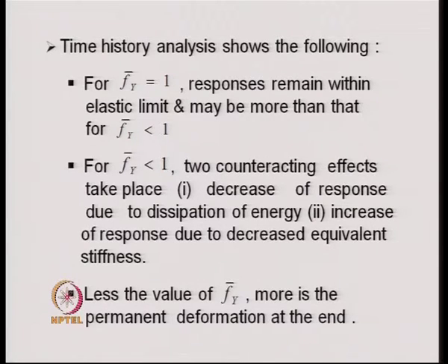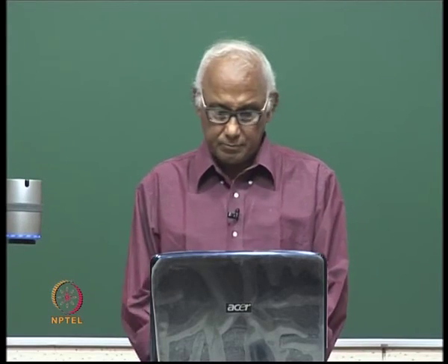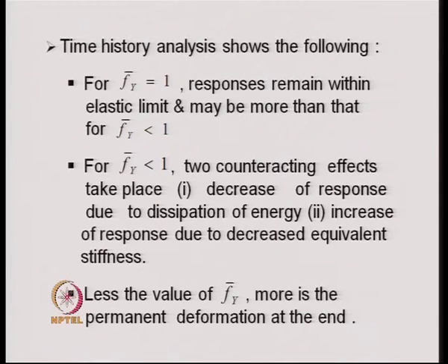Thus, the first effect tends to reduce the response of the system, the second effect tends to increase the response. Therefore, it is very difficult to say whether in the inelastic range the oscillation will be greater or less than the corresponding elastic system. The lesser the value of f bar y, the more is the permanent deformation at the end.